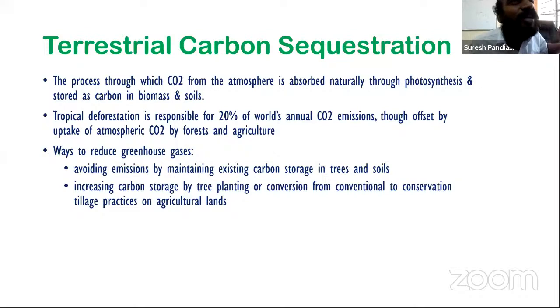In the other way, you try to increase the carbon dioxide percentage by volume by pre-combustion methods, by converting the coal through the gasification process. The third ultimate method is you try to produce oxygen from atmospheric air and then supply oxygen. When you supply oxygen, your final products are only carbon dioxide and water vapor. You condense the water vapor, which is so easy, then whatever is left over is pure carbon dioxide. Okay, theoretically, there are solutions, but then why is it still not implemented, right?